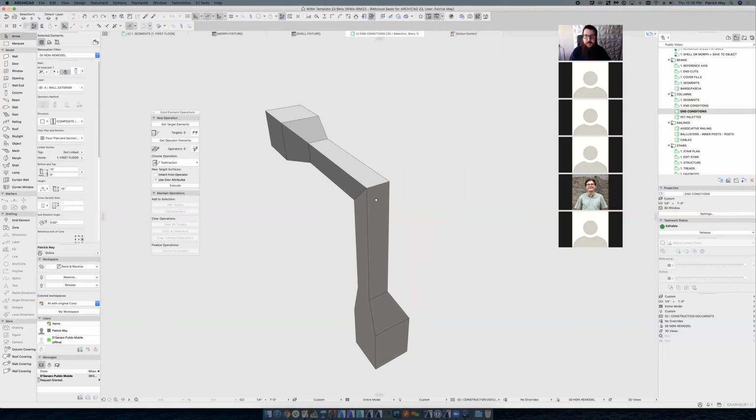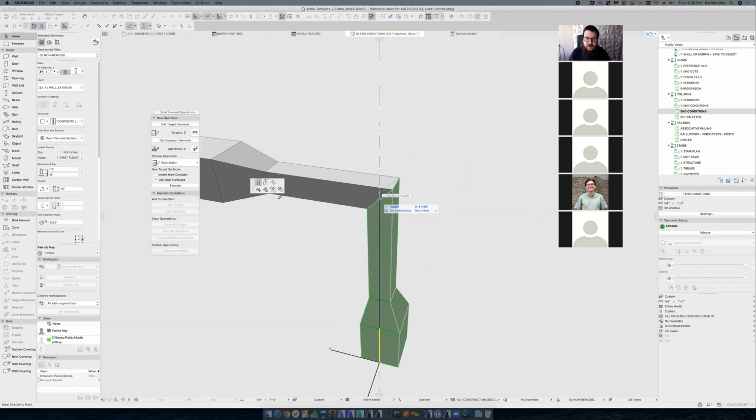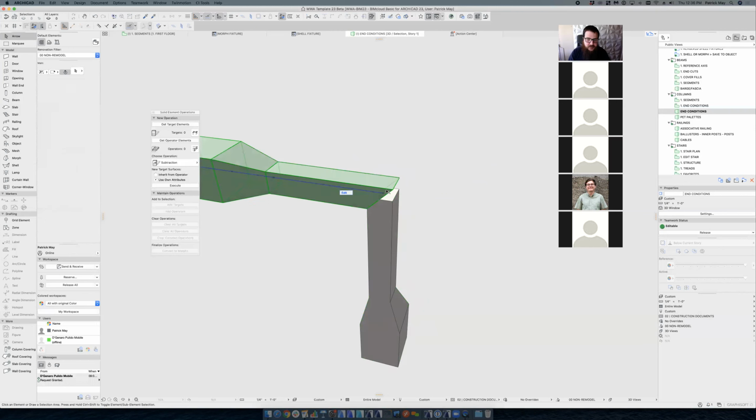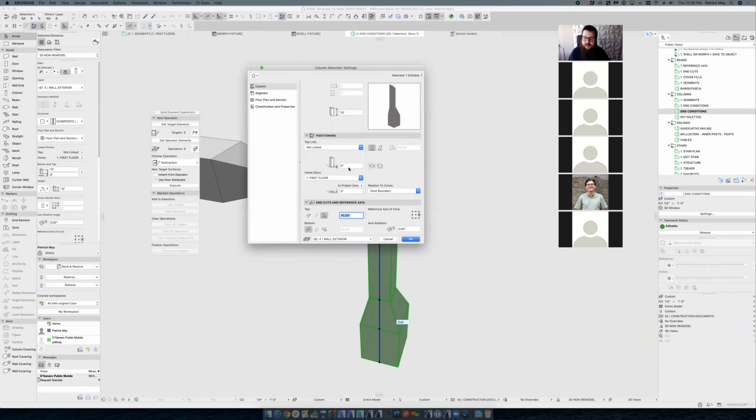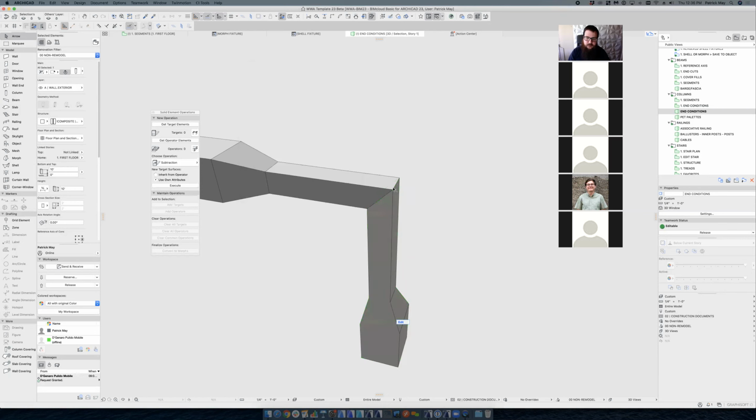A few things on the PET palettes for these beams and columns. You'll notice that there's additional options here for things like sloping the end conditions of those beams and columns. Other than that, the PET palette's pretty similar. You know, the end column, the slope, the length, all of those are the same. But that rotate end condition, you can actually do that directly in 3D with the PET palette. So if it's something that's not necessarily at a 45-degree end, as this condition is, you can actually figure that out in 3D by snapping to references and using that PET palette option.